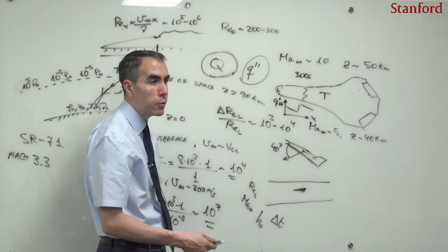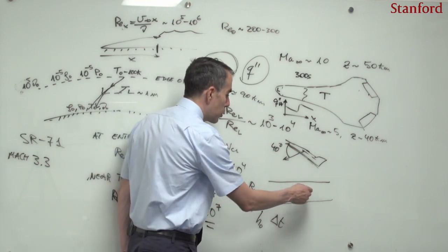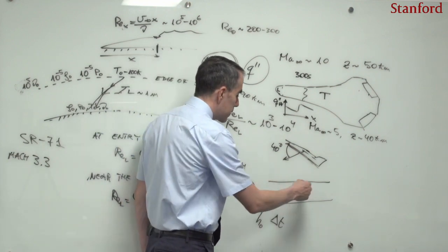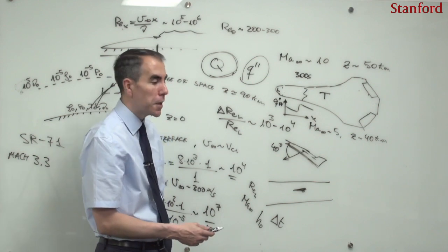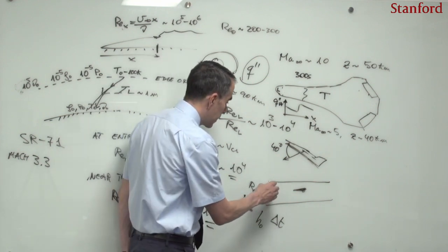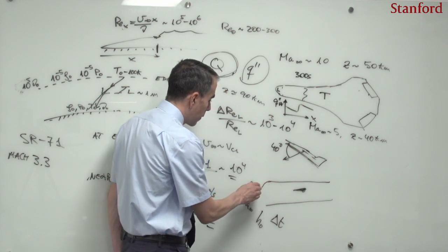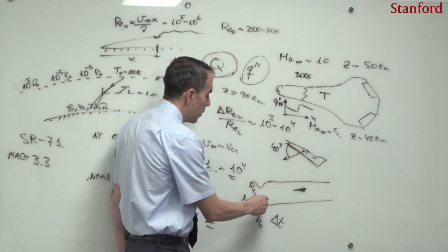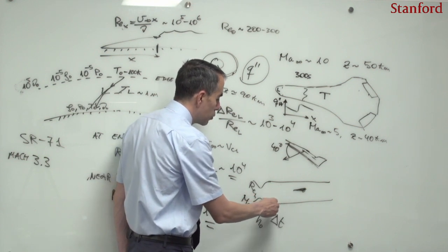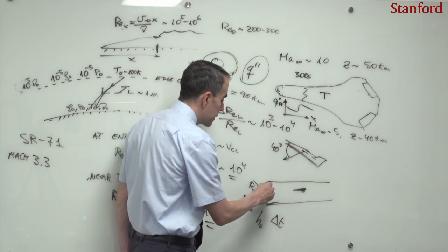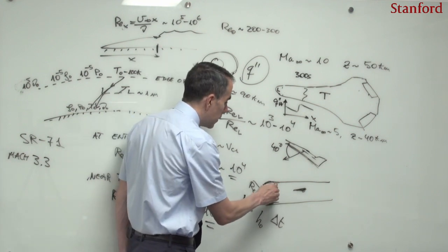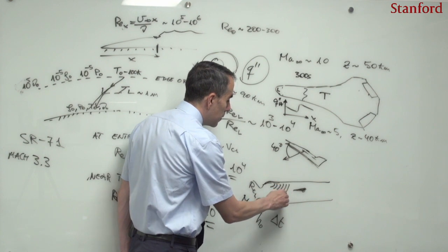But on top of those limitations, there's also another limitation related to boundary layer transition. And it is that many of these wind tunnels, with very few exceptions, have environmental noise, in the sense that here along the walls of the nozzle, and along the walls of the tunnel, there are boundary layers, and those boundary layers radiate acoustic waves.